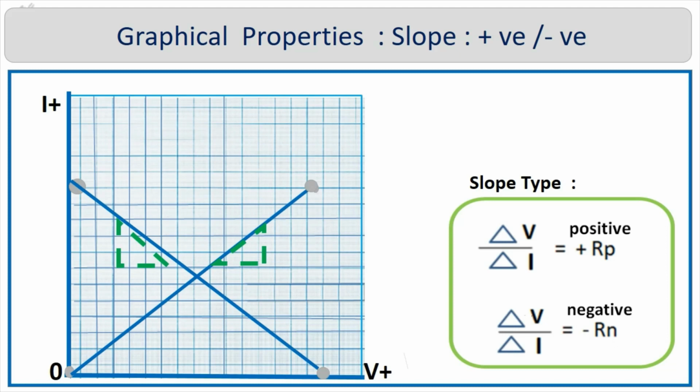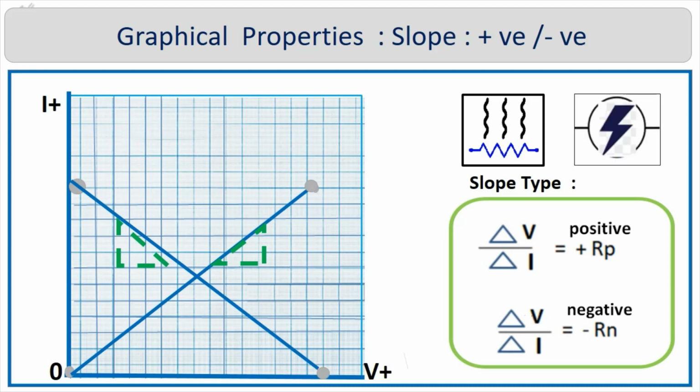This behavior is not very common and is observed in specialized devices like tunnel diodes and gunn diodes. The resistance of these devices is also sensitive to temperature. The figure shows VI graphs of opposite slopes. A positive slope device undergoes Joule heating and acts as a dissipative element. On the contrary, a negative slope device can be used as an energy source.